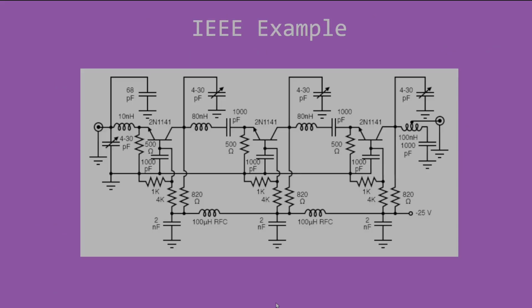All right, here we have an example circuit in IEEE. You should be able to recognize most of these symbols from our previous video. You'll notice ground symbols, there's a lot of those. Inductors, measuring the values here, nanohenries and whatnot. You got a bunch of resistors, those show values in ohms. You've got both regular capacitors and then you've got variable capacitors. We haven't really looked at the variable capacitor symbol much yet. You've got nodes, those are little dots, including the ones that apparently have a circle around them. You've got wires, and then also you have value labels too.